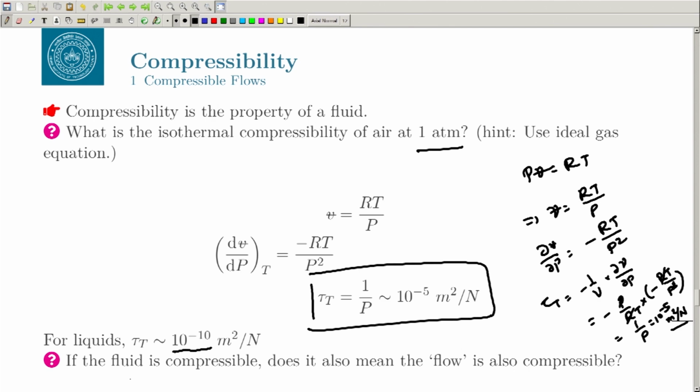But when the fluid flows, it may flow with a certain velocity, and based on the condition of the flow, there may be some properties which will be varying. For example, how turbulent the flow will be depends on the condition of the flow, not the fluid. So, the question is, when will we say our flow is compressible? We are taking a gas, an ideal gas or air. We expect that because it has higher compressibility, the flow may become compressible, but at what condition should we say that the flow is compressible? We will discuss that in the next class. Thank you very much.